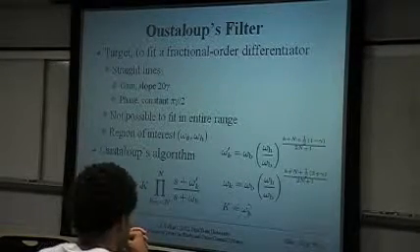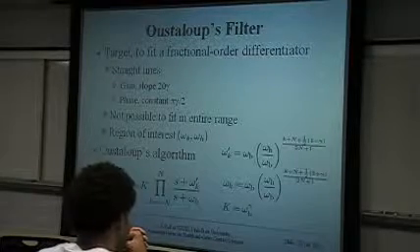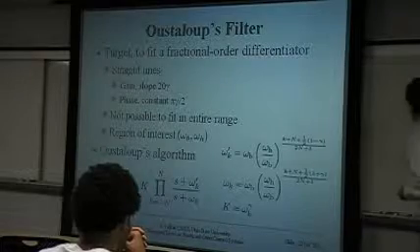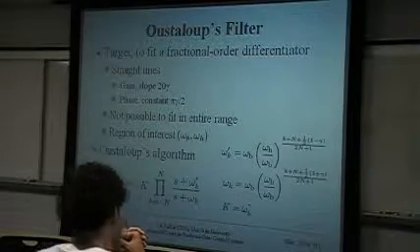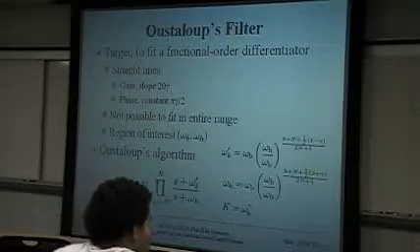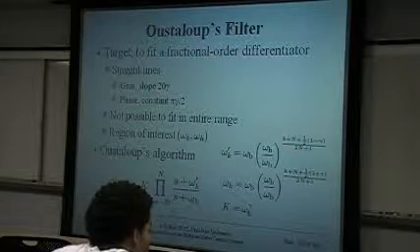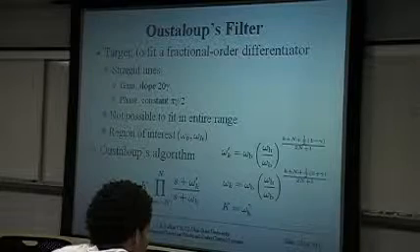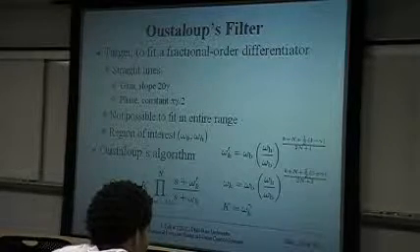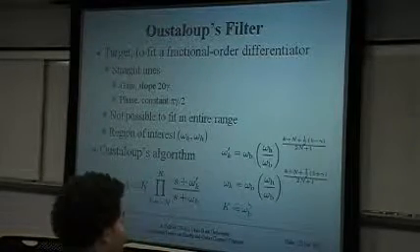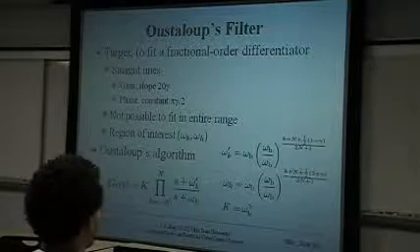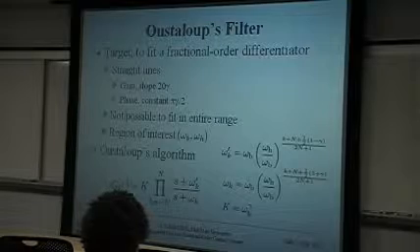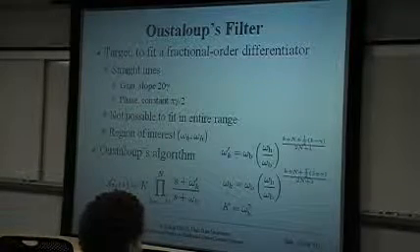It is a straight line in the Bode diagram. And the phase plot is also a straight line, a horizontal line, which is pi gamma divided by 2, where gamma is 0.2 in this example. So for a pure fractional order differentiator, the Bode diagram should be straight lines.